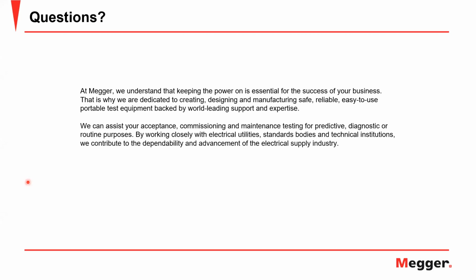All right. Sugosh, next question's for you. Do you need a recloser system, or can the 79 element in a relay and breaker accomplish the same requirement? Yes, it is possible. In this setup, the breaker itself will be performing the tripping and reclosing action based on the currents that it is seeing in the circuit, and then the relay settings also for the 79 element. So the 79 logic in the relay will be monitoring the action of the breaker.